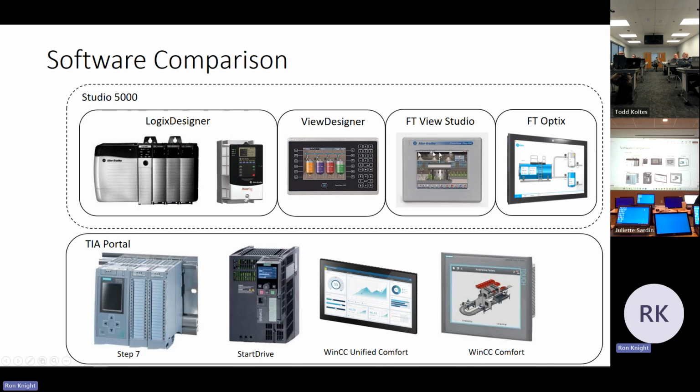If you're going to program one of their HMIs, all three of those are separate software packages. If you're programming the newer PanelView 5000 family, you would use View Designer, a standalone software package. If you're going to program the older PanelView Plus 7, FactoryTalk View Studio, a standalone software package.